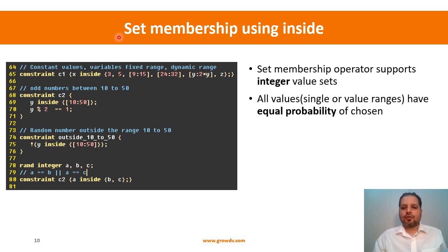Now in the next few slides, we will go deeper into each of the operators that we can utilize within the constraints, and how they help us generate different types of constraint random stimulus. That is what we will focus on in the next few slides. We'll start off with one of the very useful operators that we will use in the constraints for many problems: the set membership, or the inside operator.